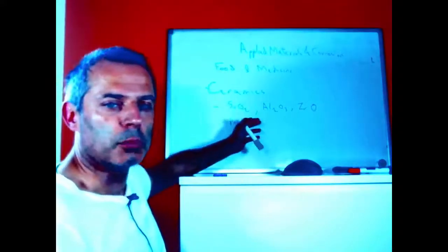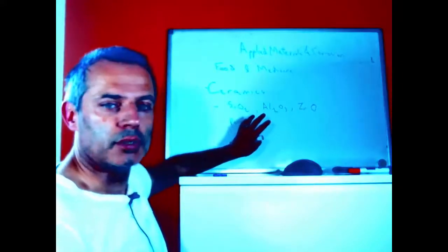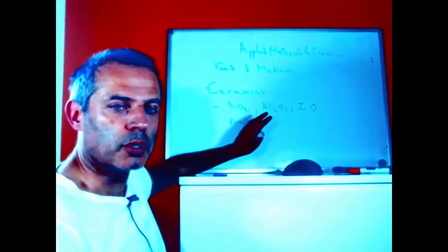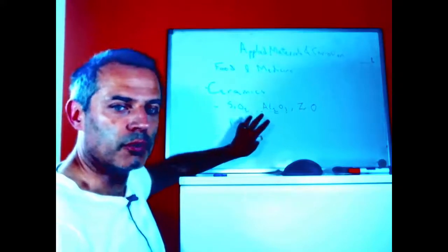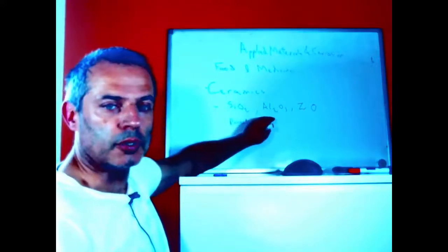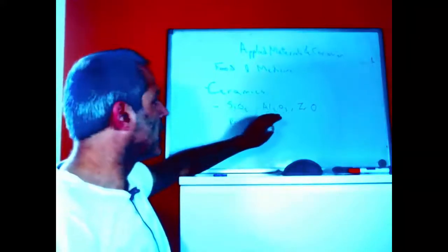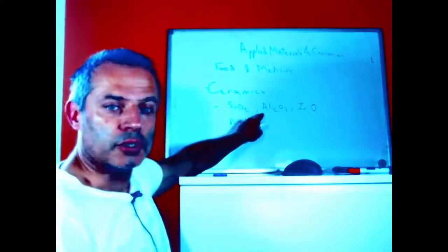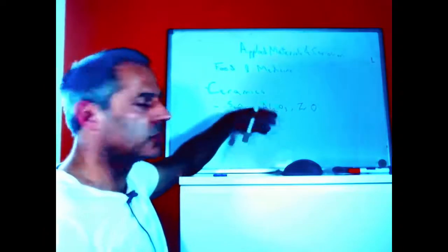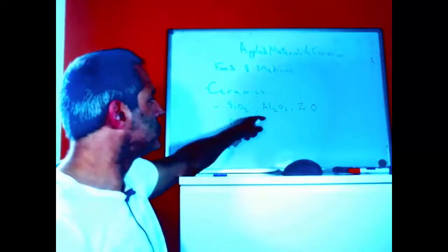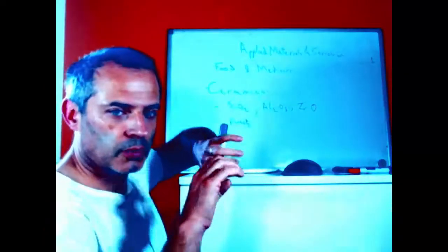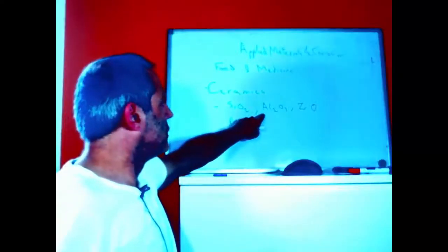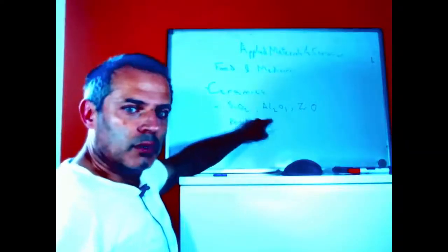Aluminium oxide is harder to melt fully, and so we tend to have a porous ceramic, but that can be a very, very small degree of porosity, and it's just the grain boundaries are not the same crystal structure, so it's not completely melted and then fused. It's just annealed.